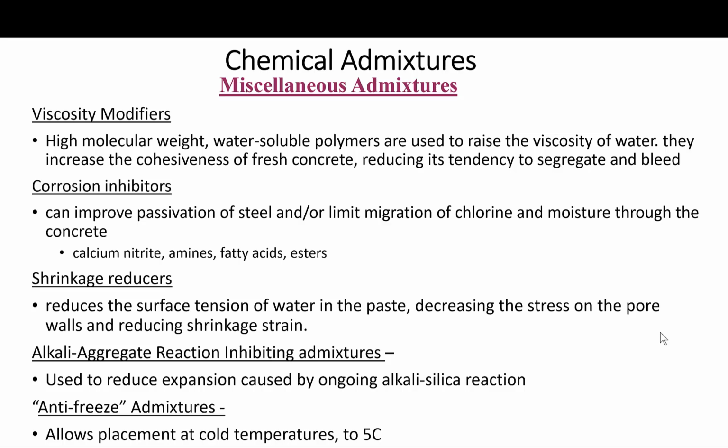Using these admixtures, although they are used not extensively, whatever value they add, in my opinion, of course, can be done with many other things that we can do to improve the concrete microstructure, basically to reduce shrinkage, combat corrosion, and reduce segregation and increase cohesiveness. So everything here can be done with certain practices and more understanding.